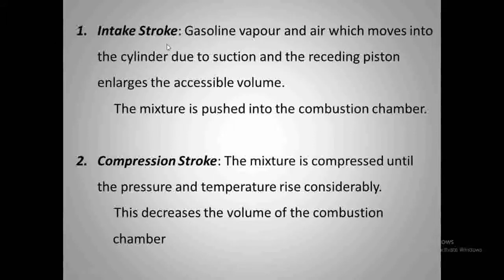So what is an intake stroke? Initially there will not be any gasoline vapor or air inside the chamber. We have to take it from outside. During this process, it is a stroke, so the piston will move and the volume of the chamber will change. The intake stroke is when gasoline vapor and air move into the cylinder due to the suction of the receding piston.